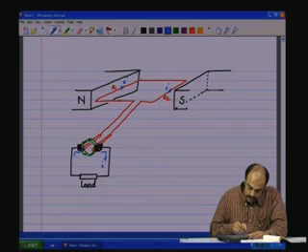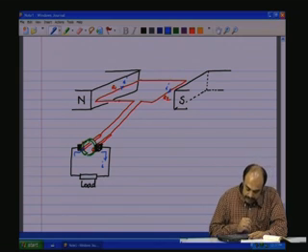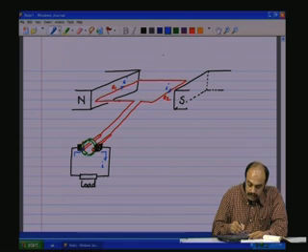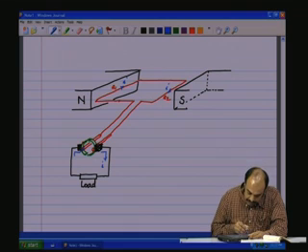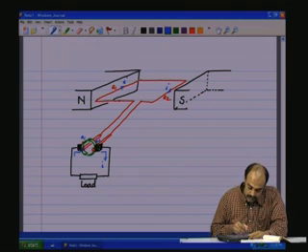The current flows through this coil. Now as the coil is rotating and comes in an orthogonal plane, the voltage becomes 0 and starts going negative. So when this has turned 90 degrees, these two splits are going to be at around the center of the brush, and then on further rotation, let us say this is A1 and this is A2 portion of the ring.